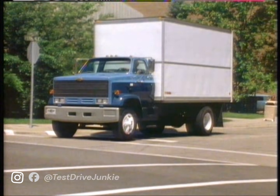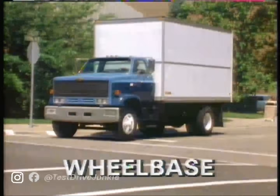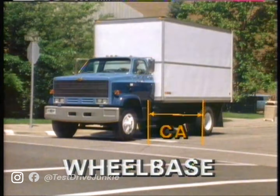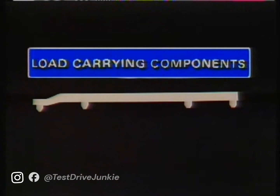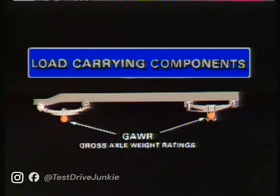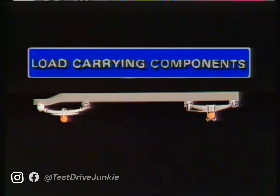The objective is to select a truck with a wheelbase that will accommodate the body. Considerations include the cab-to-rear axle length, or CA, required for the type of body that will be mounted on the frame. And since the frame is the backbone of the truck, it must be strong enough to do the job and fit the body installation requirements. The front and rear axles must have gross axle weight ratings, GAWR, that can handle the total weight of the truck and its load. Weight must be distributed so the front and rear axles are not overloaded. The medium-duty data book has detailed sections to help you select these components.